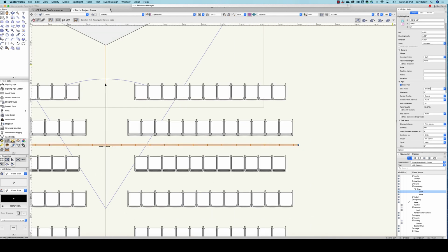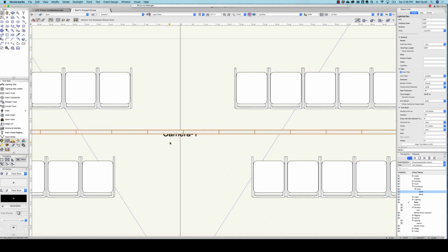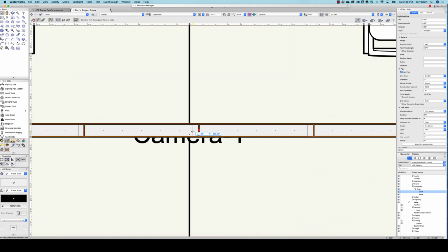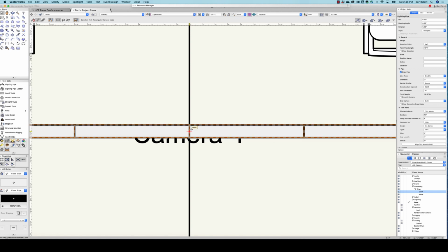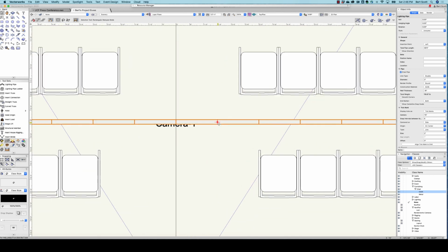So back to this for a second. The single line is there. The double line is there. These are tick marks. You can have none, or you can have a variety of different types. The reason you want these is because there's generally standard lighting spacing. 18 inches apart is the standard, and so this defaults to putting a tick mark every 18 inches so that you have a guide when you're hanging the lights. I'm moving this, by the way, so that the center of the pipe is centered here, so that you have a guide to hang the lights.